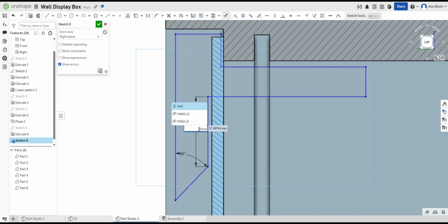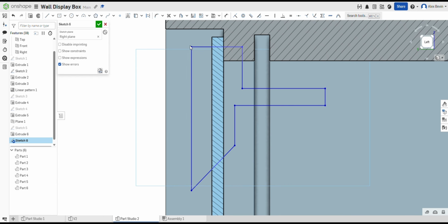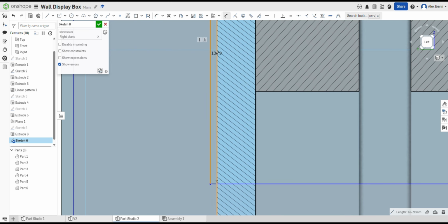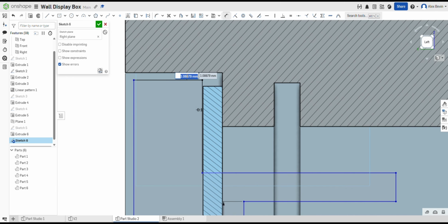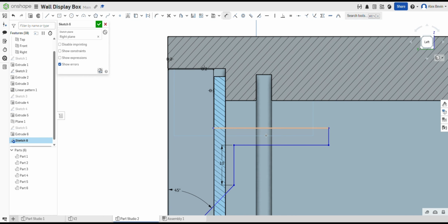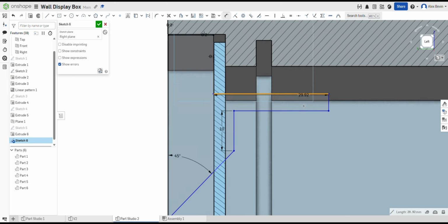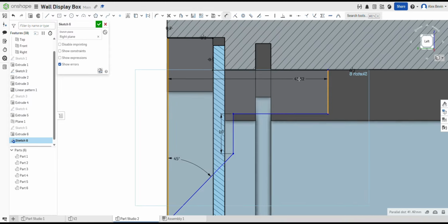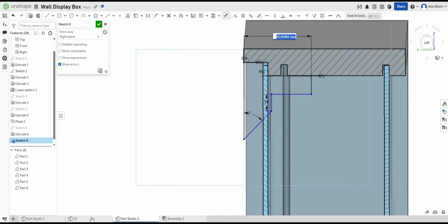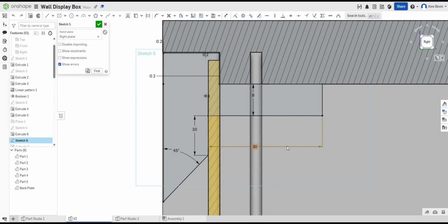Step 2. Start a sketch and rough in the cleat shape. Now I add a new sketch on the right plane. I'm going to draw a rough cleat profile first, then we'll add proper dimensions afterwards. So I'll sketch the main shape from memory. It comes down, then it slopes on the 45-degree face, and then it returns back to the base. If you overdraw lines, that's fine. We'll trim it. Now I'll use the trim tool, the scissors, to clean up any extra sketch lines and close the profile.